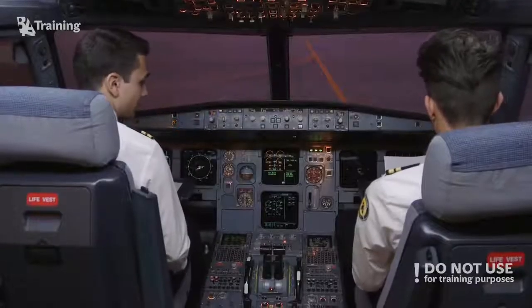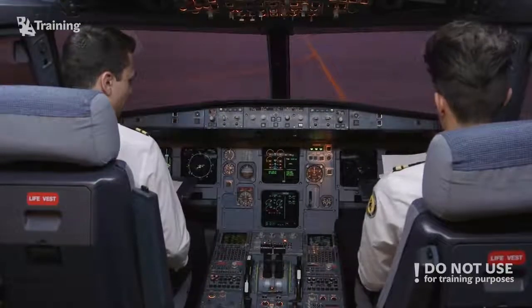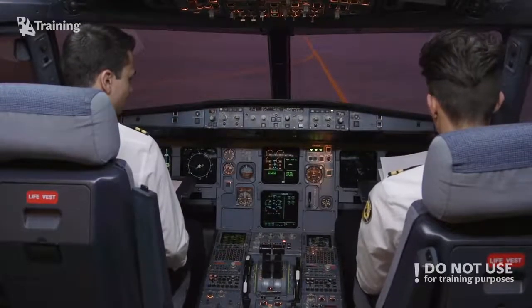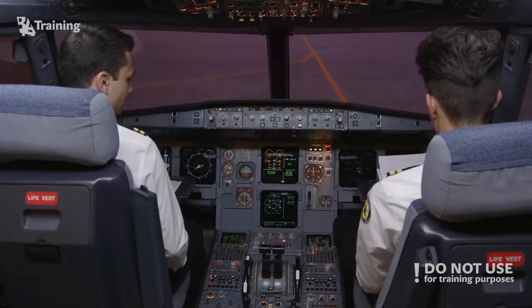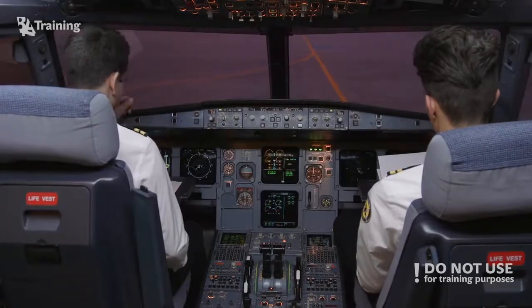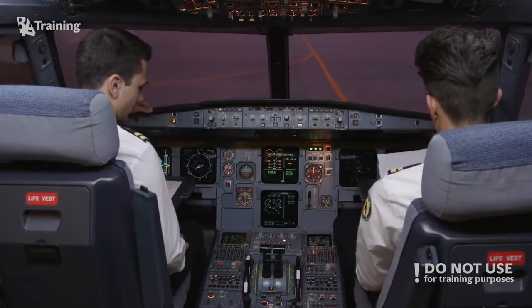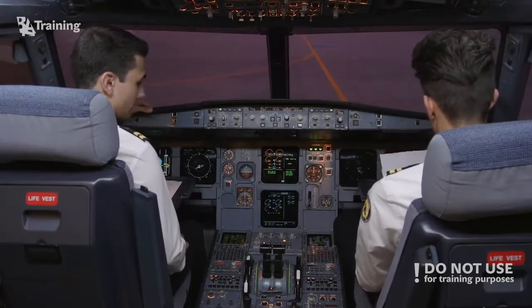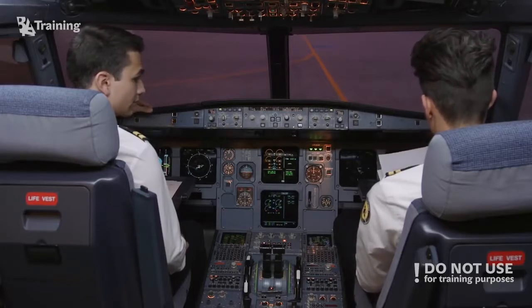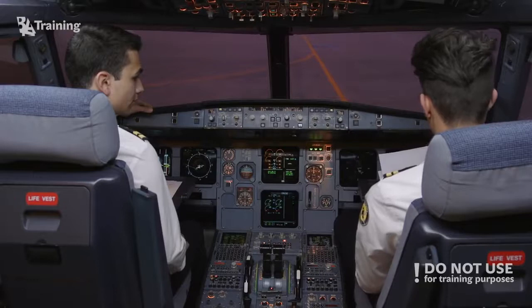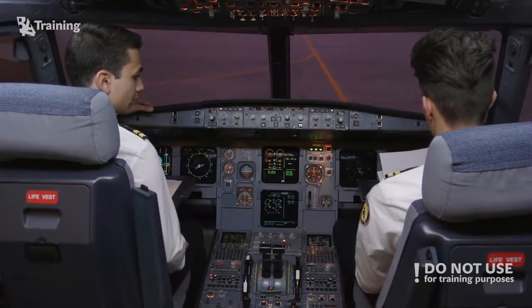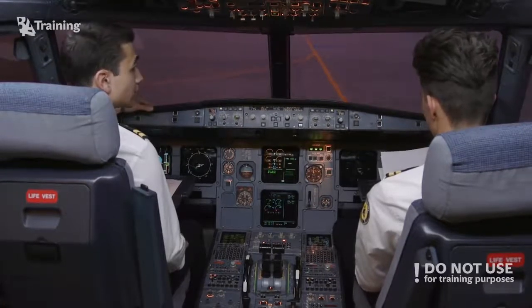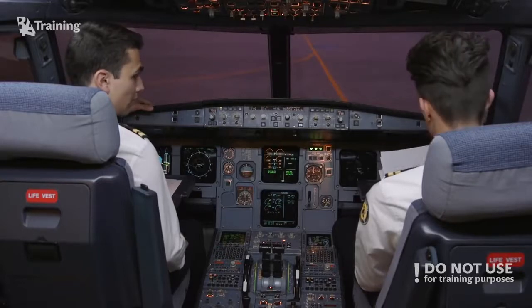Okay, continue checklist. Continuing, if needed, shed also blue electrical pump off, fuel crossfeed on, fuel pumps except right tank pump number 2 off, blower override, cabin fans off. When N2 reaches 22% of the maximum motoring speed, note, the maximum motoring speed is defined as the speed at which N2 acceleration is less than 1% in approximately 5 seconds.